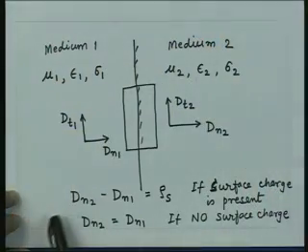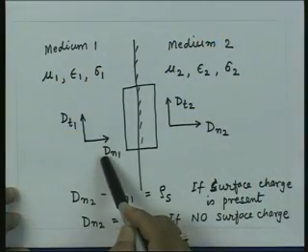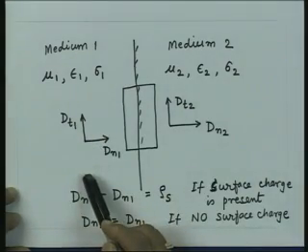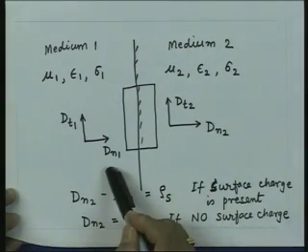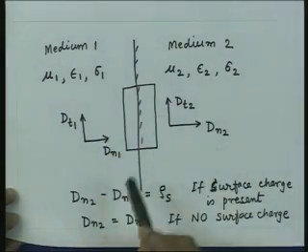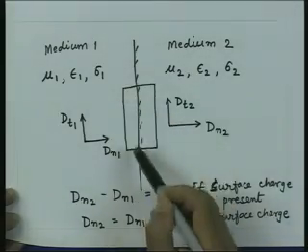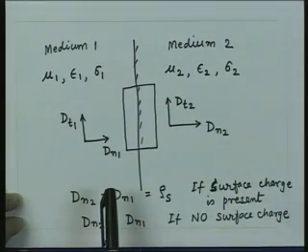So, we have a boundary condition on the normal component of the charge density. Same thing we can do for the magnetic flux density also. So, we can take again the same box like this, and instead of the displacement vector we can have the magnetic flux density, which is B, and since we do not have free charges, there is nothing like surface charge for the magnetic fields.